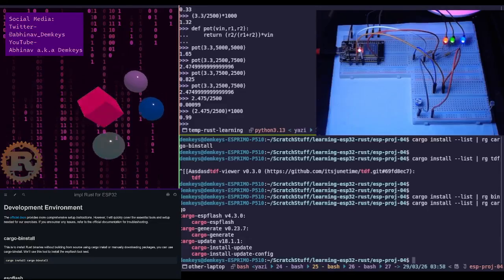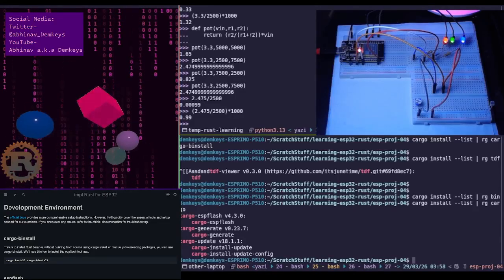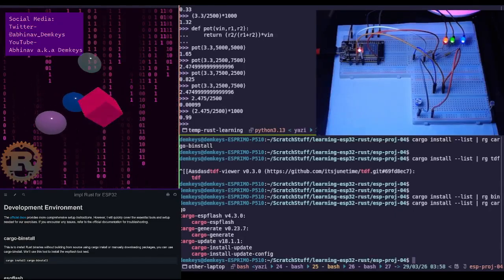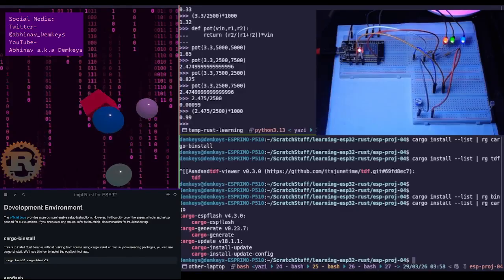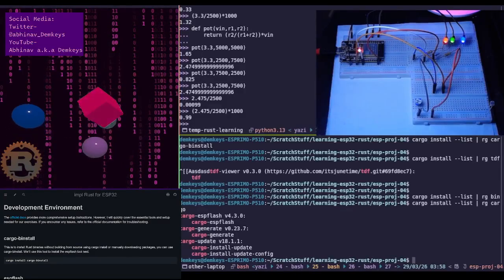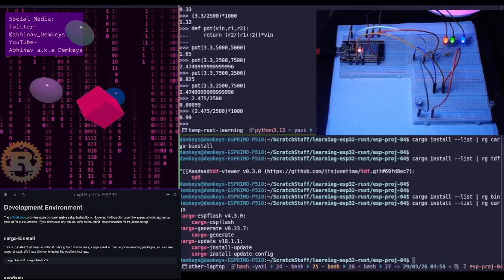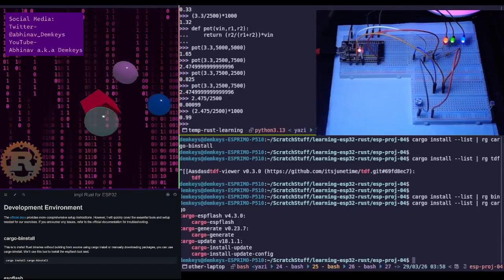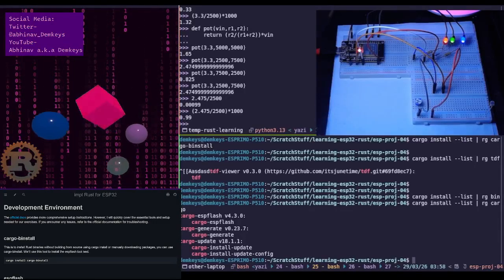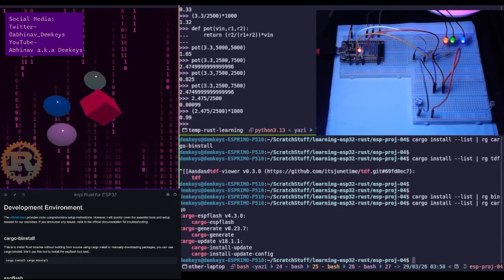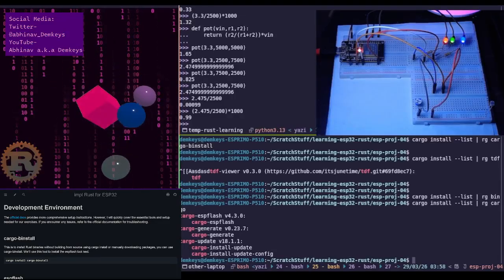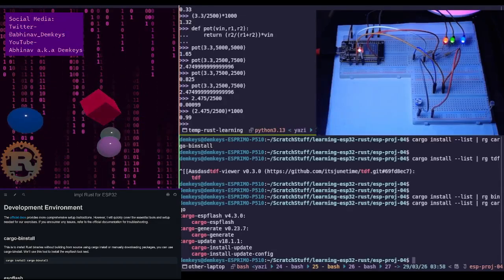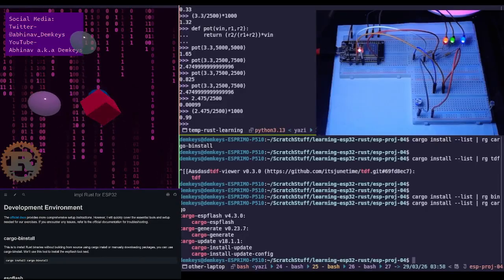However, if you need to switch higher currents while maintaining that optical isolation, there are several high current variations and strategies. Power optocouplers, these are called solid state relays. Okay, then Darlington output optocouplers. They have a slightly higher current range, not all that much.